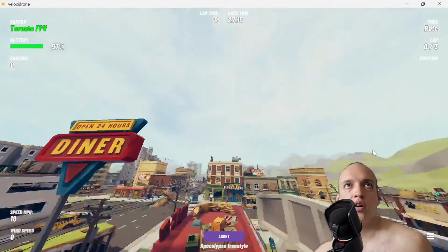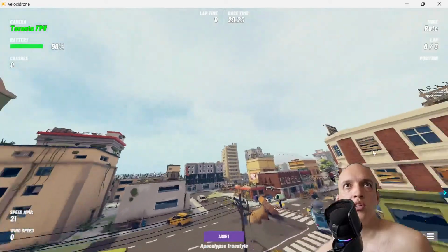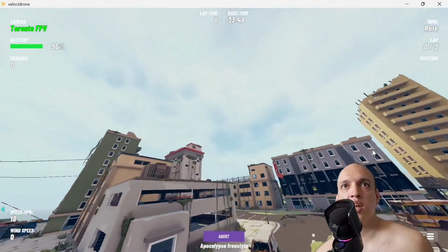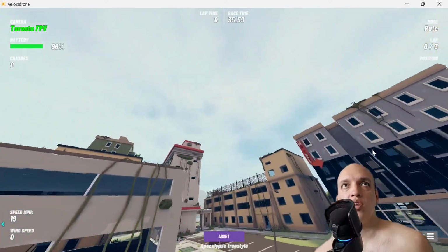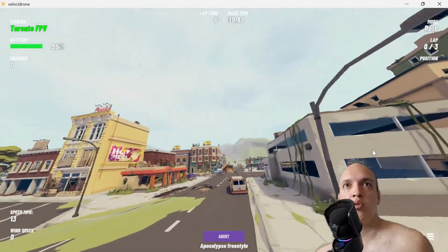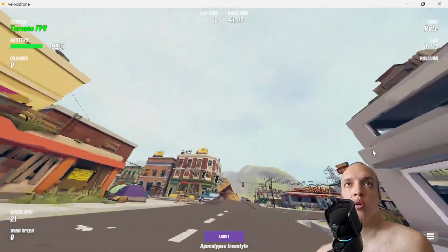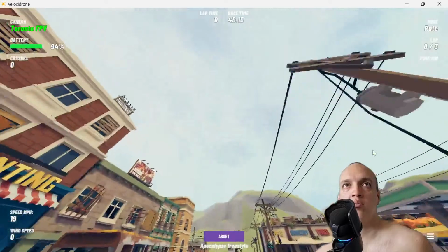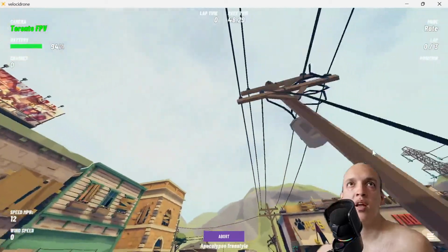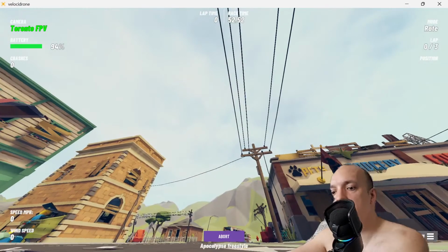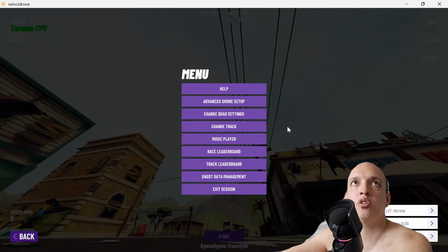So you have your throttle, and I have angle on my drone. So just by keeping it steady, I'm moving forward. You can have a lower angle, which will do less of that. You can have more angle, which will kind of pull you forward more. If you want to learn more about angles, go to my How to FPV Angles Masterclass, and it'll teach you about that. I'm going to actually put less of an angle right now, so we have to abort the race to be able to do adjustments.